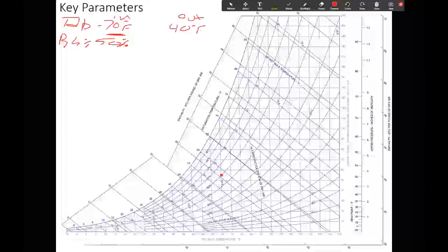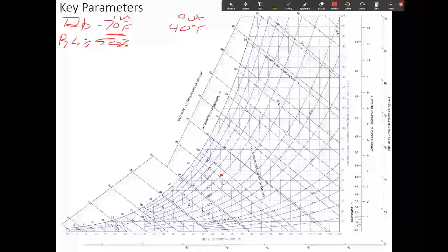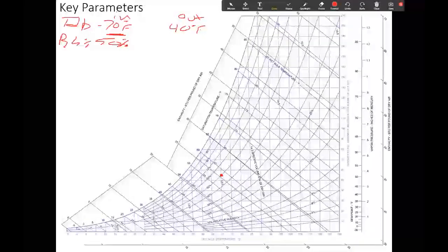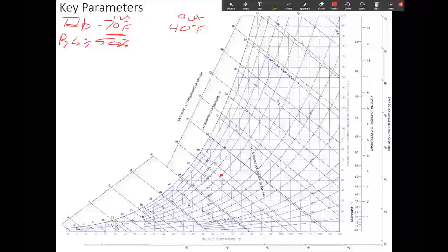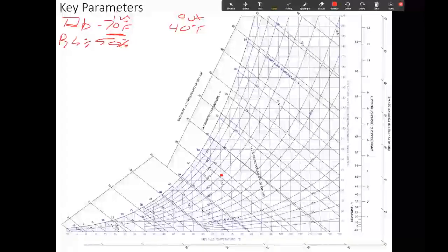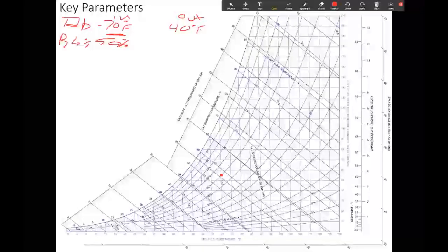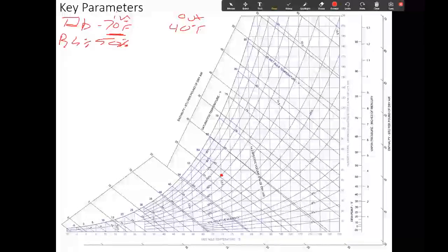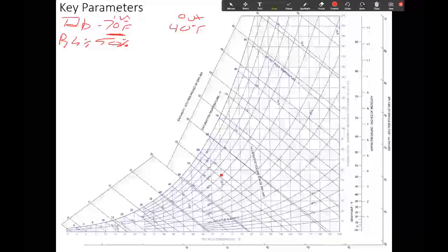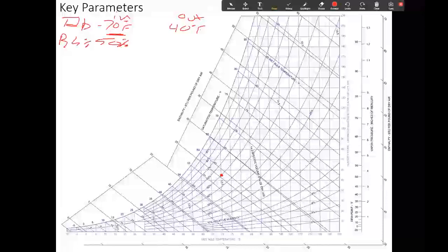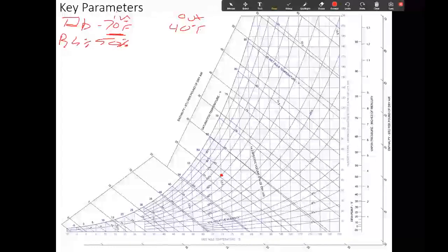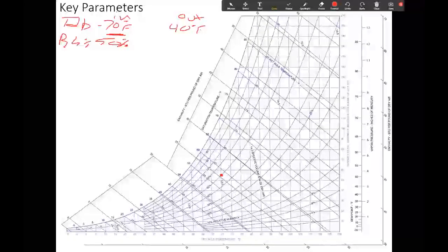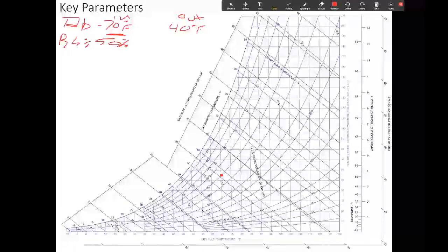What is my dew point? Anyone? Is it around 50 degrees? Yes. And what does that mean for condensation? What are the implications of having a 50-degree dew point when it's 40 degrees Fahrenheit outside? What temperature do you think your sheathing is going to be? What conclusions can you draw from the psychrometric chart in your wall design? Is it going to be around that 50-degree dew point with condensation on it? Yeah, but what does that mean for your wall?